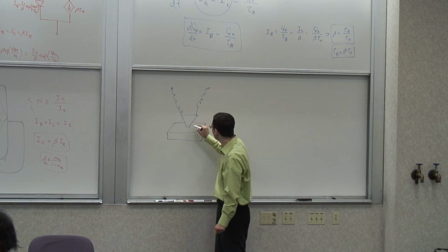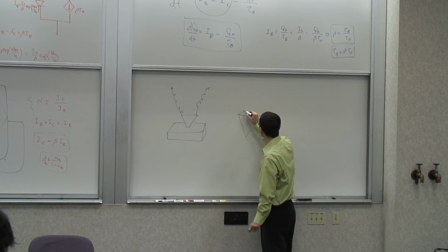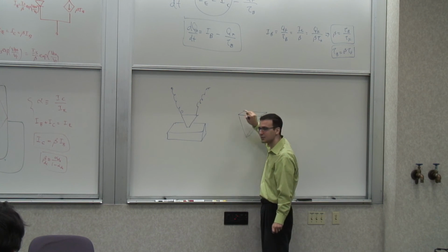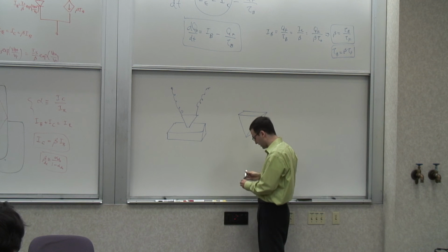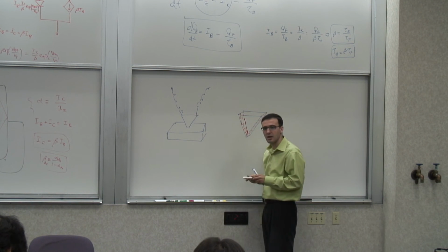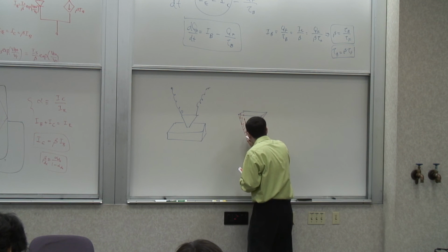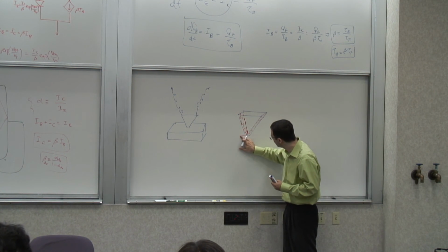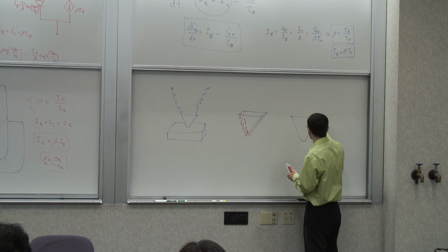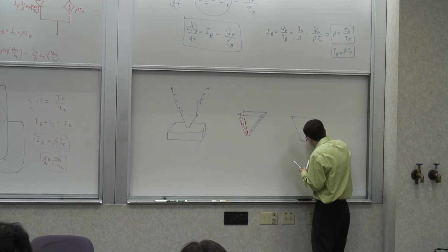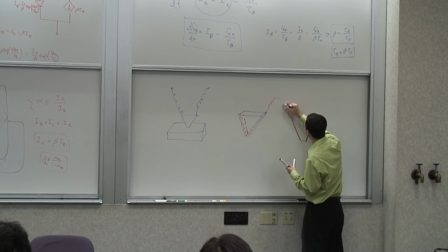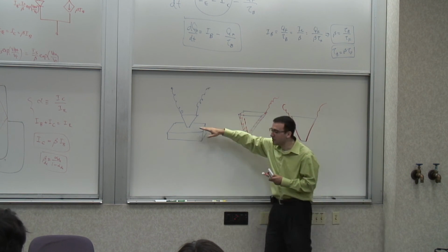Now this thing, if you look at it, was a wedge. They took a very tiny one, and then they put a layer of copper on this, kind of like a very thin copper foil, started from the side, and they had it on the other side. Then, under the microscope, they cut the tip off. If you look at the cross-section of this thing, it looks like that, magnified quite a lot. It's copper here, and copper here. Then they made contacts here with some wires that are these kind of springy-looking things, and they put it on top of the semiconductor.